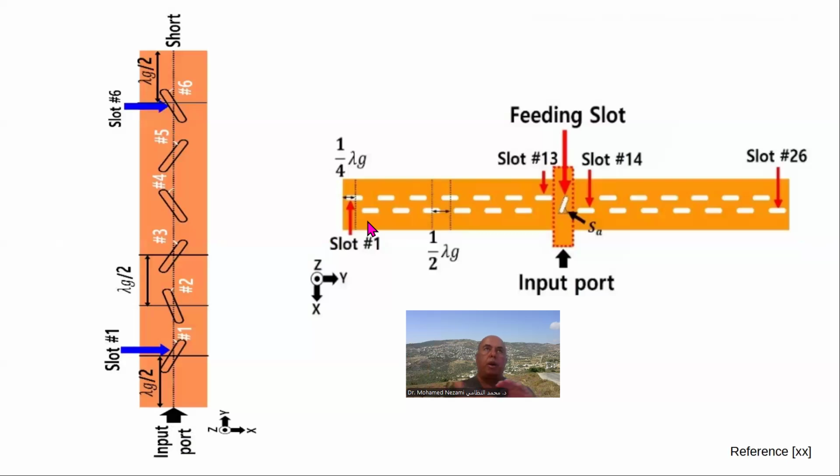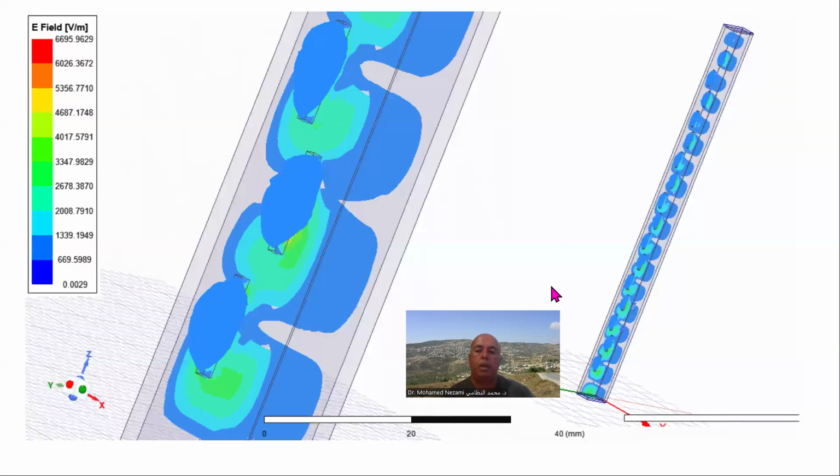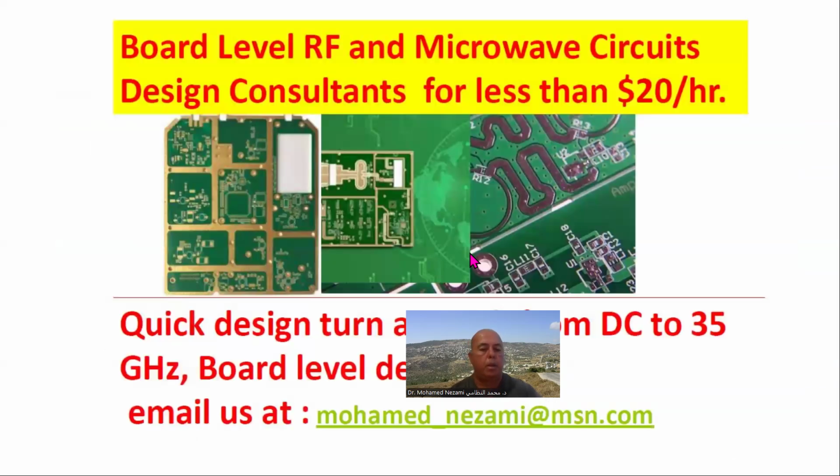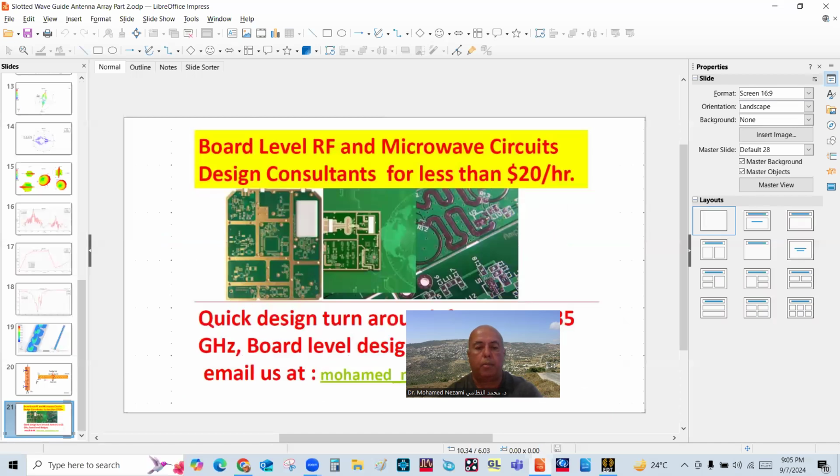And then on the bottom of that waveguide, we've got another waveguide placed at 90 degrees, orthogonal at the bottom, and it has another slot in the bottom that will radiate from the feed to this waveguide. Obviously, this one here, I'm feeding the signal from this side. I'm going to replace that with this mechanism in here, because that's how you would have it in actual systems. Okay, so let's go back.